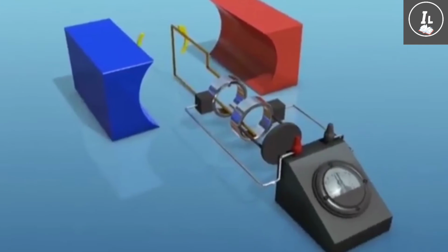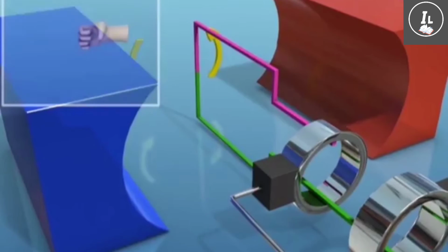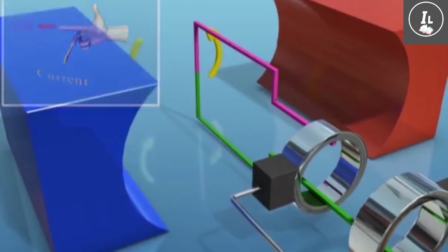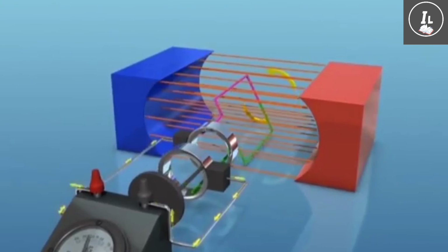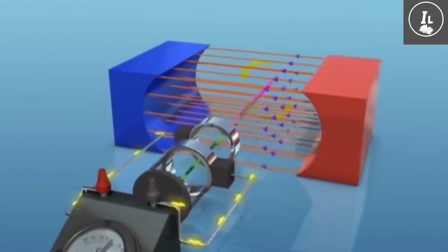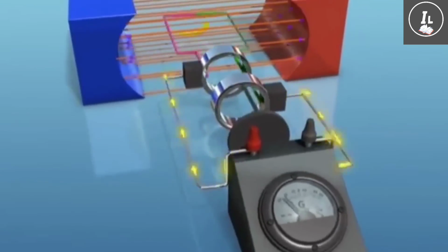To understand the generation of alternating current more clearly, let us mark one arm of the armature as green and the other as pink. As per Fleming's right-hand rule, the direction of current in the arm marked as green is outward, and in the arm marked pink is inward. After rotating half turn in anti-clockwise direction, the direction of current in the green arm becomes inward and that in the pink arm becomes outward. Thus, after every half turn, the direction of current changes and as a result, alternating current is generated.